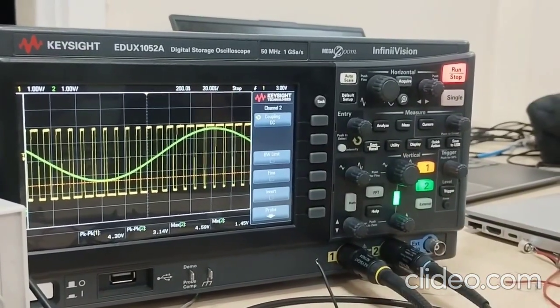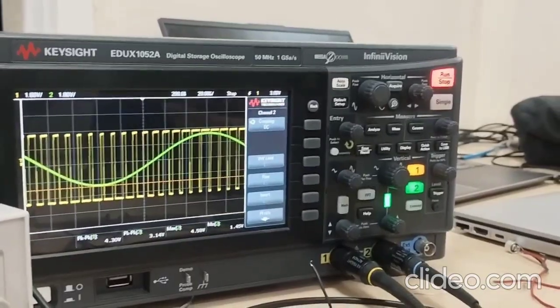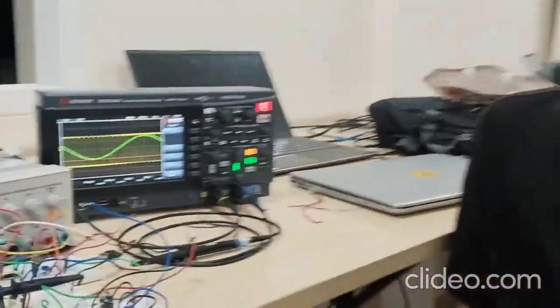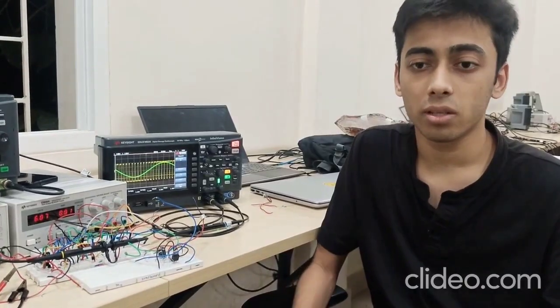Now, while using PWM modulation, care has to be taken so that the input amplitude voltage does not go beyond the triangular wave voltage. So we have to ensure that the input signal strictly has voltage less than 3 volts. This allows the PWM wave to have a duty cycle between the range of 25% to 75%. This prevents there being a complete zero signal or a complete 5 volt signal throughout.